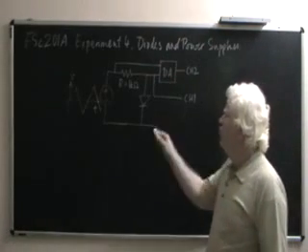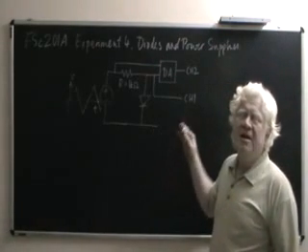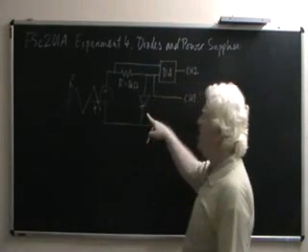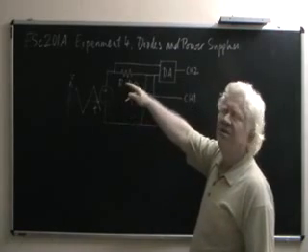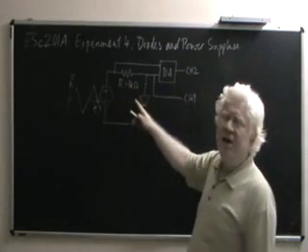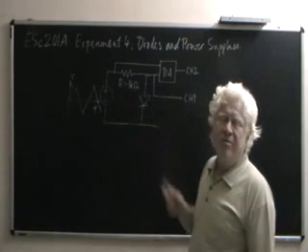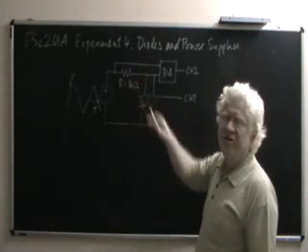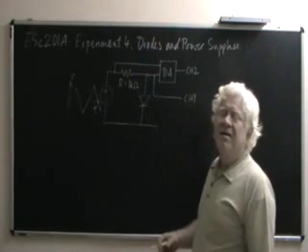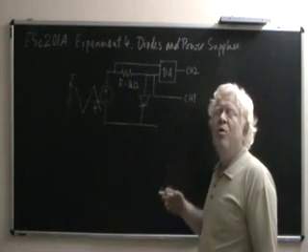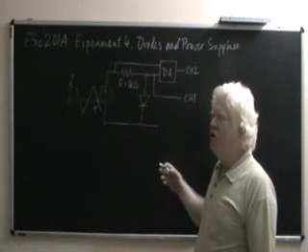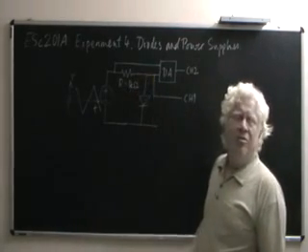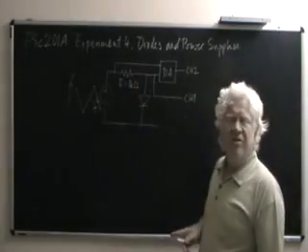So here is the circuit we use to carry out the experiment that determines the characteristic of the actual diode. Here is the actual diode under test in this place, and here is the resistor that I said you need to connect in series to measure the current that flows through the diode. Now clearly what we want to do is to measure the voltage across this resistor and recognize that being a linear resistor, the voltage is indicative, though not numerically equal, to the current of the diode and the resistor, which